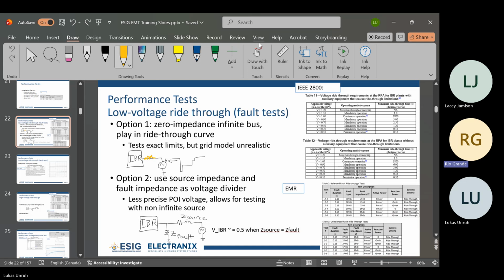Yeah, I was thinking about it, and the way we were curious how it measured up first was basically a bunch of really short duration dips that had a summation greater than the requirement over that 30-second time period. So they weren't necessarily faults; they were just infinite bus dips. And none of them would exceed the duration where they'd be allowed to trip instantly with that dip. But then the sum of them was greater than the requirement. So it sounds like, yeah. So for that one, if you see a trip, it would be due to just a counter in the model.